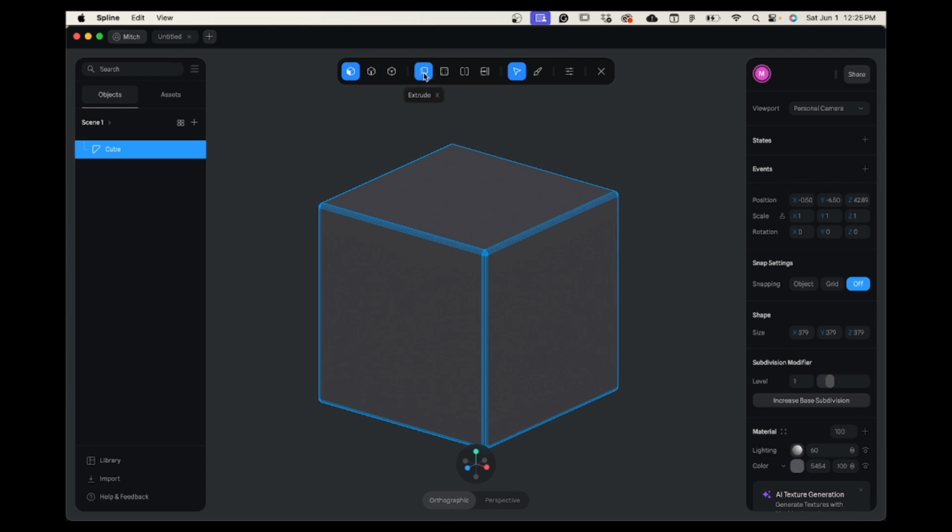Anyways, we're going to learn about the extrusion, which is a basic principle in 3D modeling. So we're going to click up here, click the extrude button, click the side we want to extrude, hold down this blue circle thingy, and we're going to extrude it, and then we're going to hold down shift on the scale button like we did before, and we're going to scale it down.